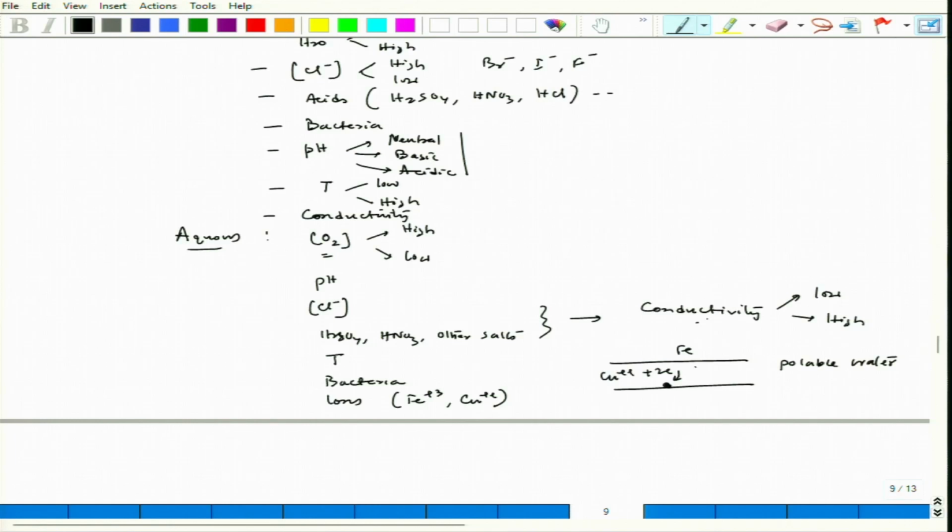So, the cathodic reaction happens there, and just by the side, more cathodic reaction would happen. So, near that place there would be a localized anodic dissolution because of the higher rate of cathodic reactions there. So, in fact, there is a possibility of leakage.